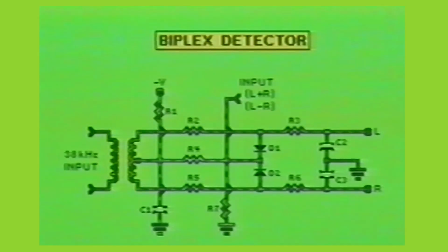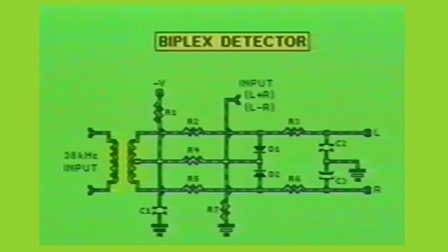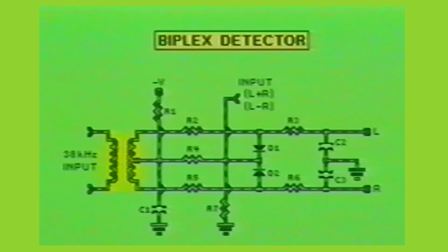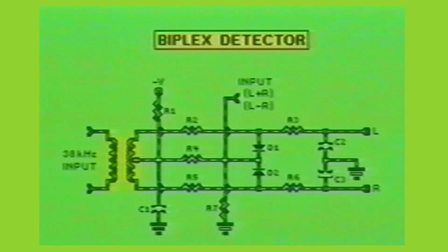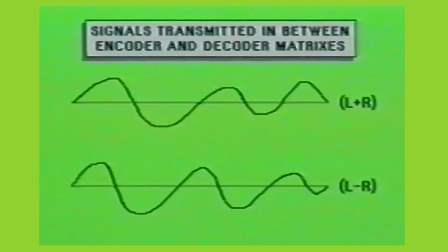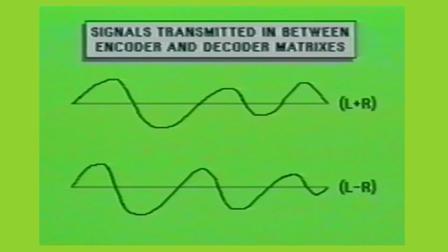Remember, this entire circuit is designed around reinserting the 38 kHz subcarrier with the L-R signal and using the L-R information from both sidebands, just as a simple one-diode AM radio detects information from a single sideband. The extracted L-R information is now at the same audio frequencies as the L+R information, and the actual left and right audio channels may now be isolated into their independent soundtracks.